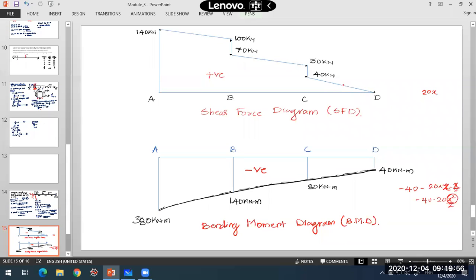The variation of shear force is linear here. Only when we are across concentrated loads is there a sudden change in the shear force at those points. Other than that, where a UDL was present, the variation is linear, increasing uniformly. In some cases we see that the shear force remains constant also.